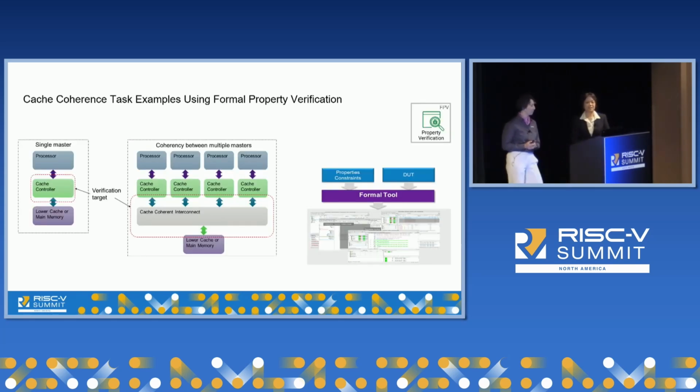There's also another way of using VC Formal, the FPV app, to verify cache coherence. Quite commonly, people build a formal testbench, again using properties and logic to build the constraints and the checker properties to thoroughly verify the cache coherence. It's challenging because formal gets state explosion, so it may be difficult to get full convergence on these kinds of properties. But whatever assertions and assumptions you write are not wasted. They can be fully utilized in your simulation run to catch bugs there.